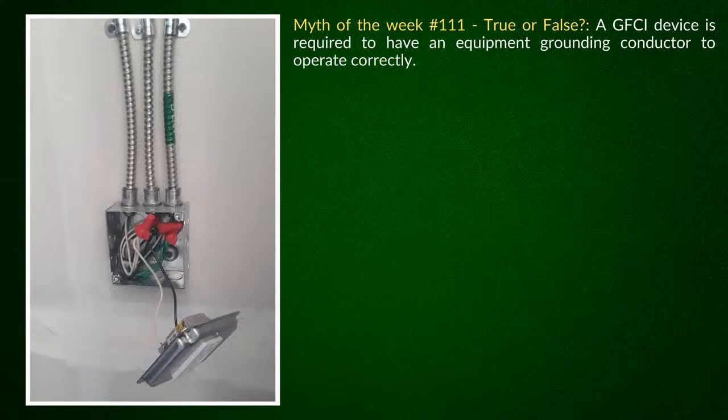So that's the only really approved way to do it anyway. The little button on your GFCI head is actually not an approved way to test the device, because it's not giving you the actual trip. I actually have a really fancy one that I got from Klein. I ran it a few tool reviews ago, but it actually is approved, because it trips it between the hot and the neutral, and it gives you the trip time and all the different stuff. So that would actually be an okay way.